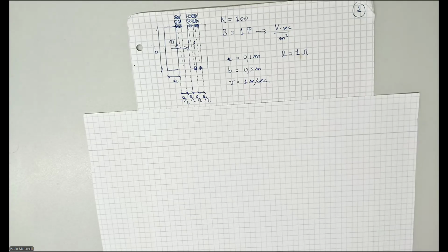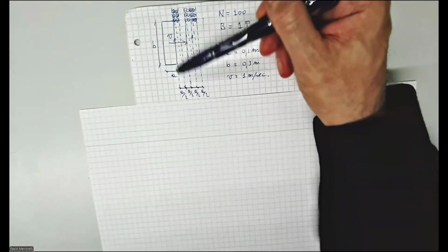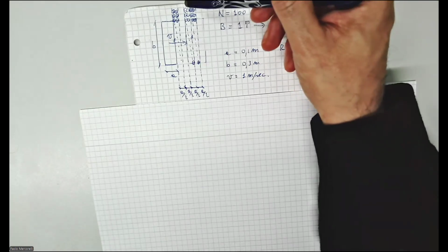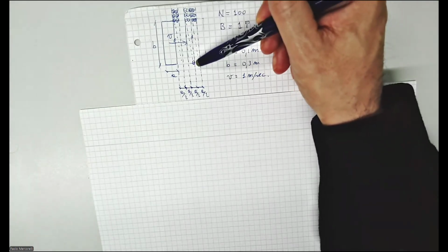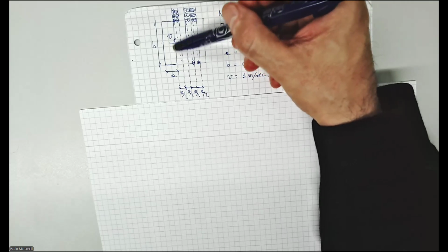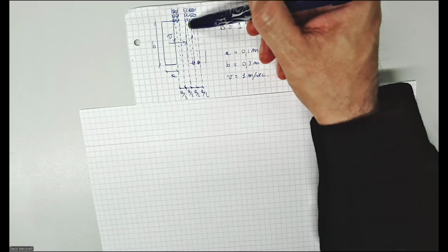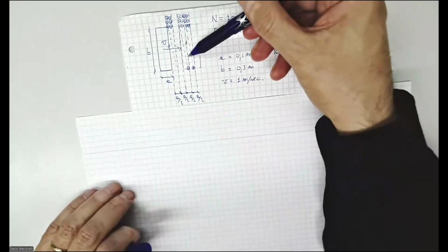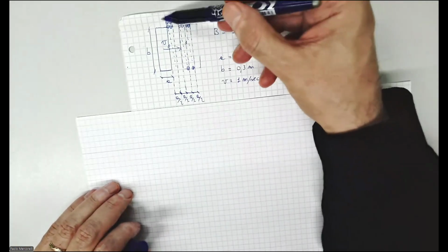I give you a couple of minutes and then I will start to show you the solution. Question: is the flux positive, then no flux, and then negative and positive again? It is positive at the beginning, empty as before, negative exactly as before, and then please pay attention, the last part is positive. This means as long as these conductors are here, or until here, better to say, no changes, but from here it changes a lot when this conductor is here.